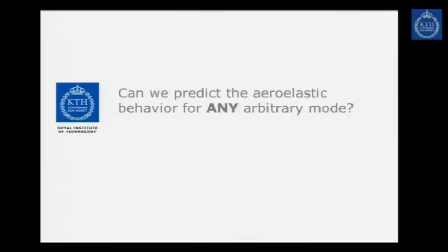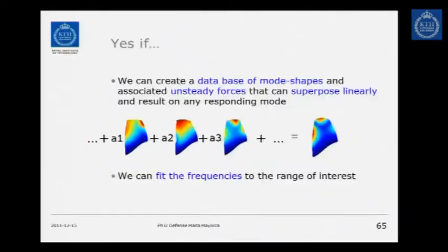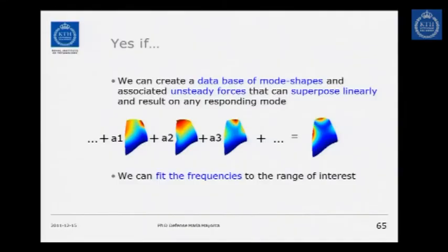So now the last question that I ask is, can we predict the aeroelastic behavior from any arbitrary mode, not knowing my in-vacuum mode? So yes, if I can create a huge database of mode shapes and associated unsteady forces that can superpose linearly and produce any mode that I want. So that's one hand. And second, if I want to model any mode shape, I can also say I want to predict any frequency range. So I need to have a model that allows me to fit the frequency on the range that I want.